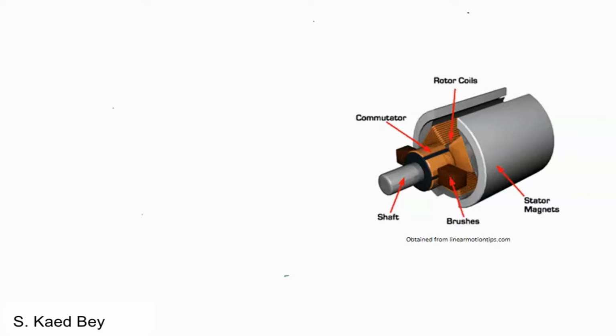Generally speaking, dynamic systems are presented by differential equations. For this DC motor, we can start from the applied voltage. We can consider the electric circuit as such. So we have a voltage input. We can assume that the windings have a total resistance R and an equivalent inductance L. Now R and L represent the actual rotor coil within the motor.